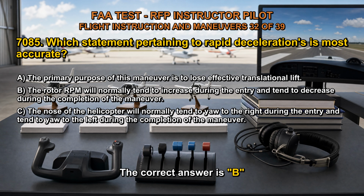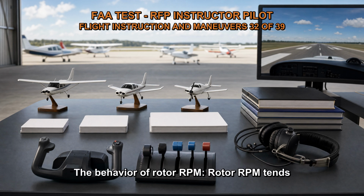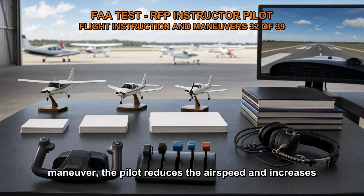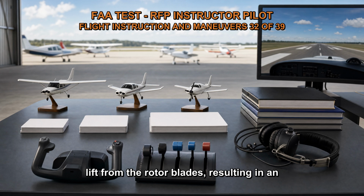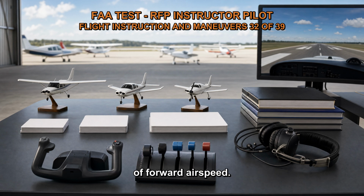The correct answer is B. When considering the characteristics of rapid deceleration maneuvers, the behavior of rotor RPM tends to increase during entry. During a rapid deceleration maneuver, the pilot reduces the airspeed and increases the collective pitch to create a high rate of deceleration. This sudden increase in collective pitch generates more lift from the rotor blades, resulting in an increase in rotor RPM. The increased lift helps counteract the rapid loss of forward airspeed.